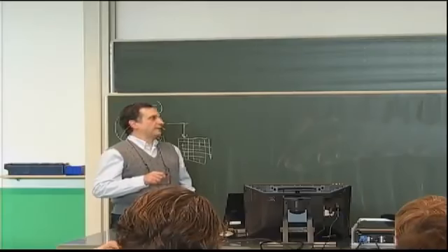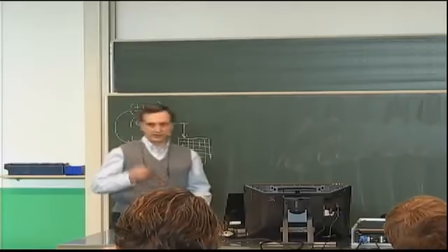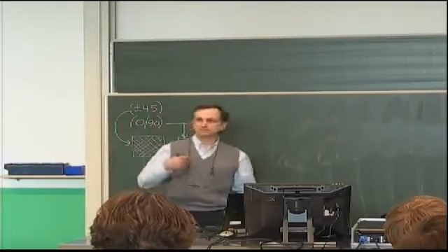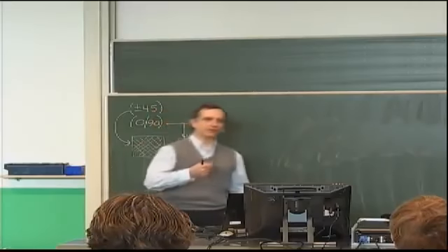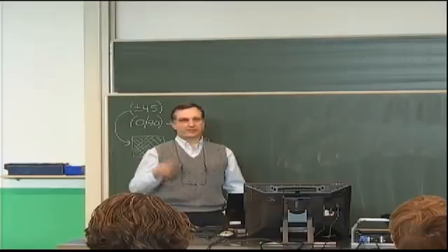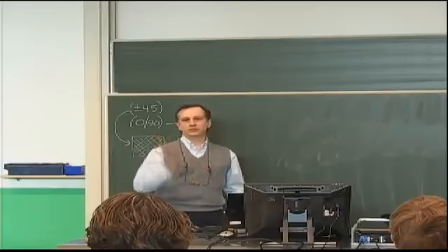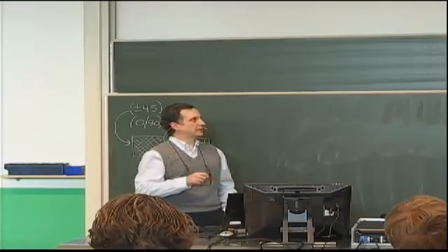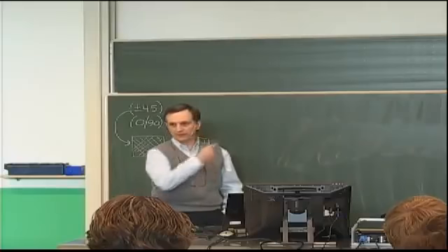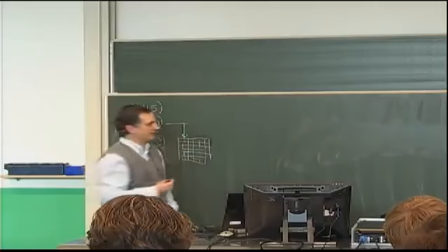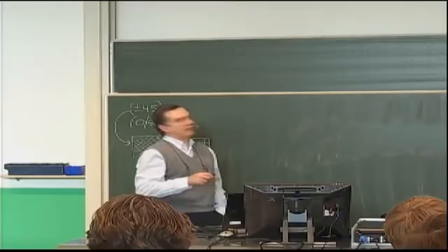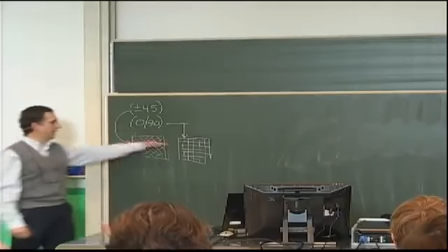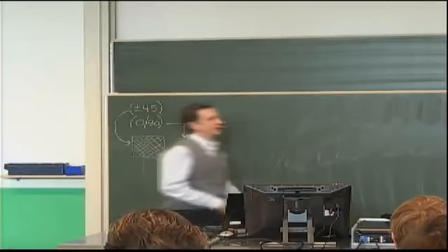And so I'm doing only 3 different laminates just to see the different trends. This doesn't mean you would only use those, and you would need either a more rigorous way of picking your laminates or definitely some other perspective that says, okay, if for some reason we need to use this type of laminate, make sure you include it in the ones you compare. What I've done here is I've included the plus or minus 45, 4, which is the one we have been checking so far to compare with finite elements, which is a very soft laminate because the fibers are in the plus or minus 45 direction, then in plane in the 0 and the 90 direction has relatively low stiffness.